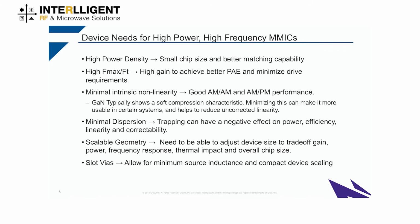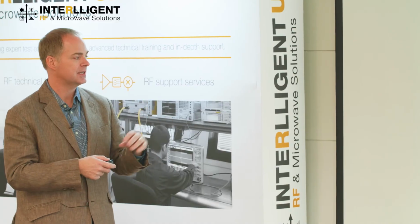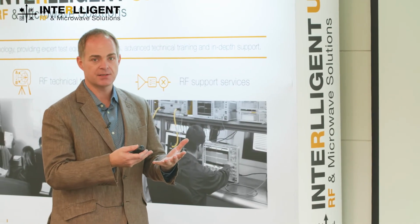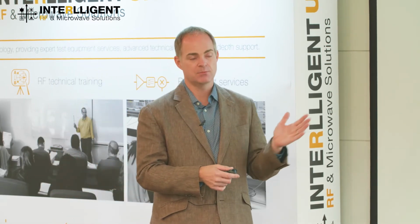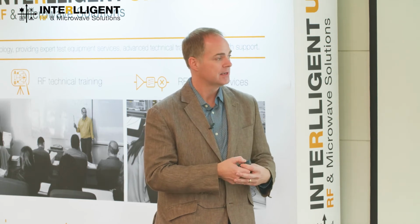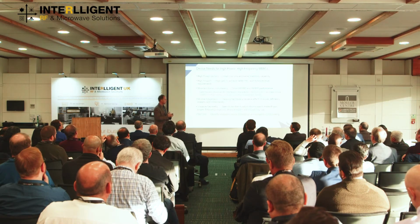And then scalable geometry. In order to make a good MMIC, you need devices and models for those devices that are scalable to the exact sizes and geometries that you need, applicable to the power requirements and frequency requirements for your application. And last but not least, to really move into the highest frequency, having integrated slot vias in the devices allows you to minimize the source inductance, which is a key aspect to moving the knee frequency of the devices out and making them more applicable at higher frequencies without having to actually shrink the gate width and reduce your power.